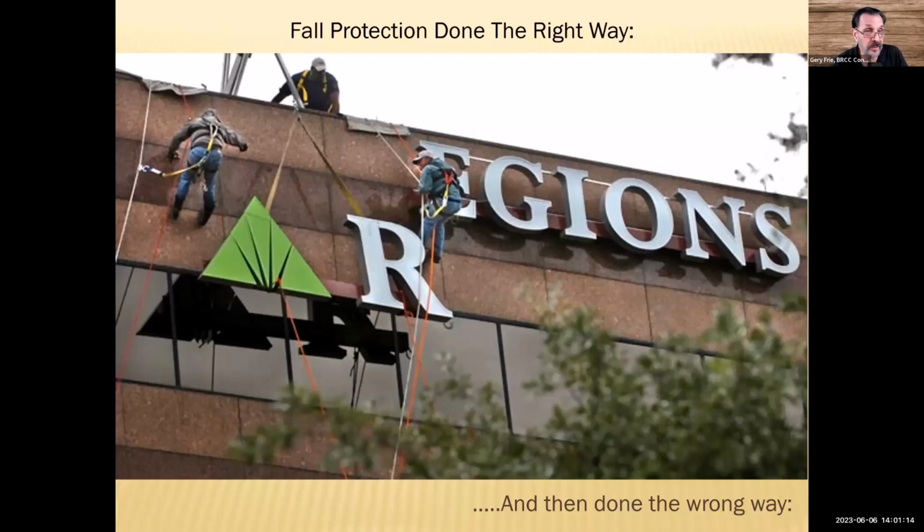There's a couple of things I can see wrong with this picture. The guy on the left dangling should have that rope grab up higher. It should always be tied up above you, not below you, because that means he would fall a lot further than 2 feet. The third guy up at the top on the roof looks like he doesn't have his chest strap connected.